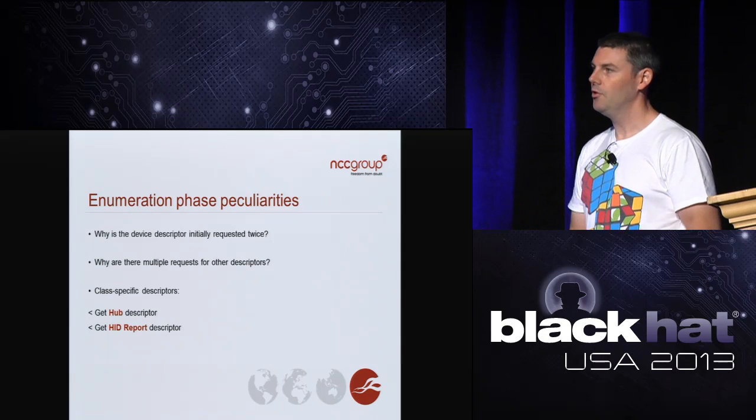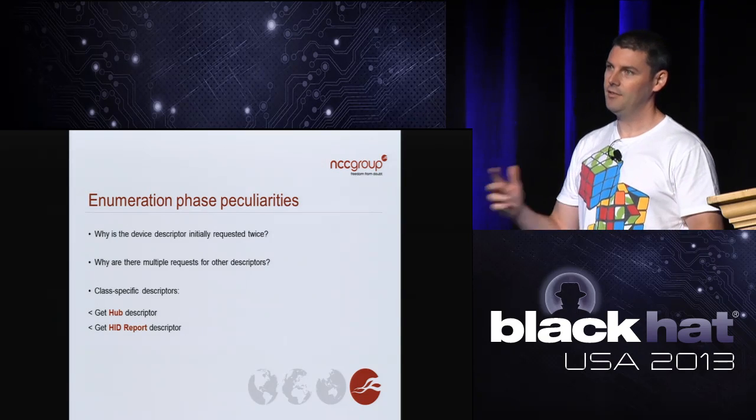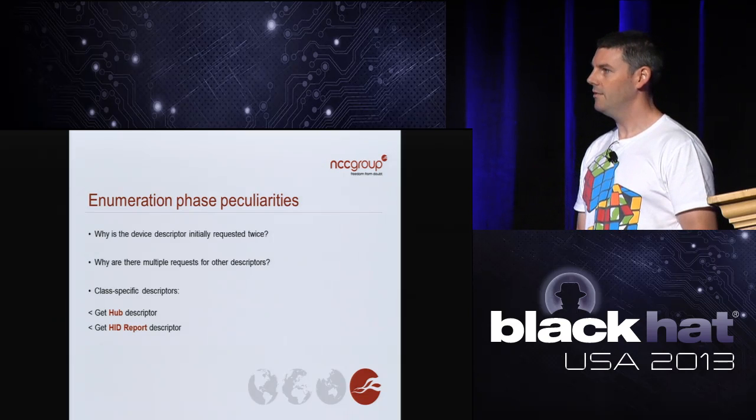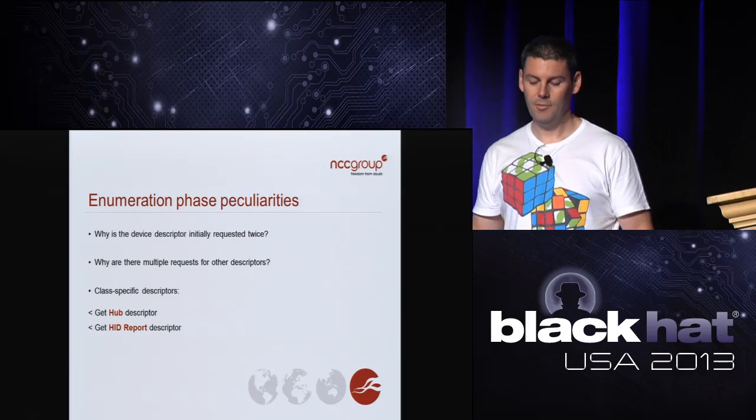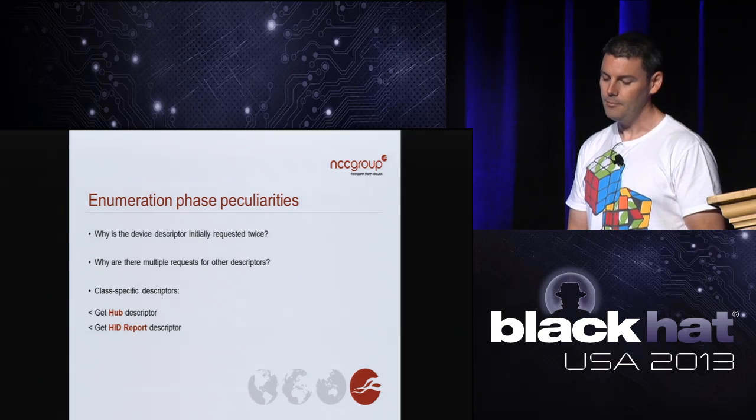After the host has decided on an address that it will use to communicate with the device, it resets that device and then starts the whole process again. So it resets the device but with that new address, so it requests that device descriptor the second time.